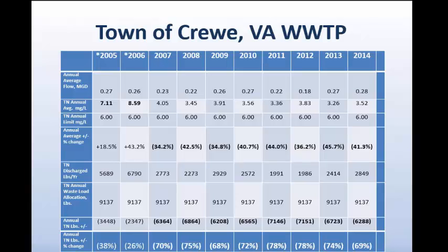Here in Virginia, we have a total nitrogen discharge pound allotment, and that comes because we are regulated on the Chesapeake Bay watershed. The receiving streams that this facility discharges into ultimately discharge into the Chesapeake Bay. The Virginia system works, and it may work this way around the country, but in Virginia it works through the nutrient credit trading program. For example, we belong to the James River watershed, and there are a number of facilities that are part of the James River watershed.